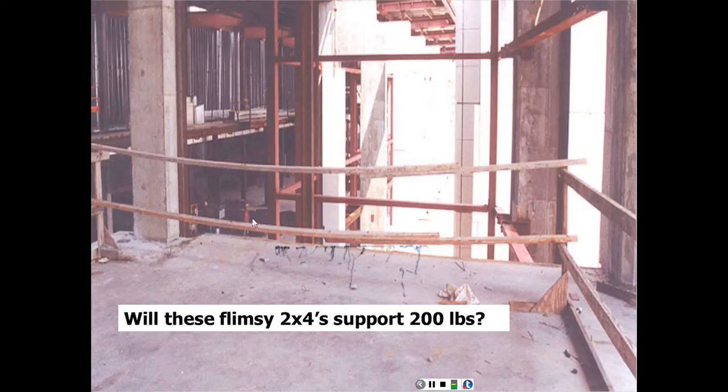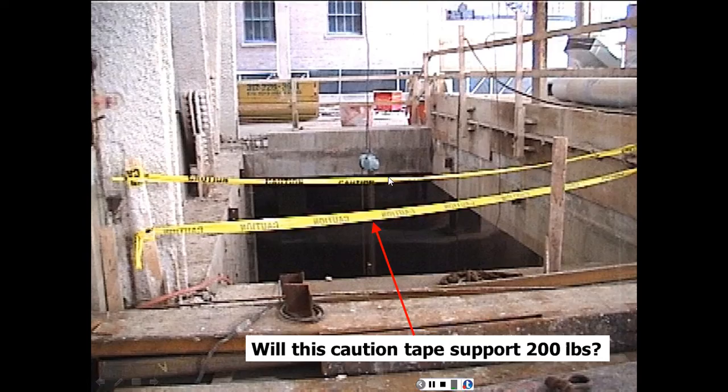So this is not going to work, and it's spliced, and it has so many defects. Definitely this is not going to work. This cannot be considered as a guardrail. It does not support the 200 pounds. The mid rail or the mid tape or whatever you want to call it is not satisfying the 21-inch average. We don't have a toe board. It's not flagged. So many different problems here.